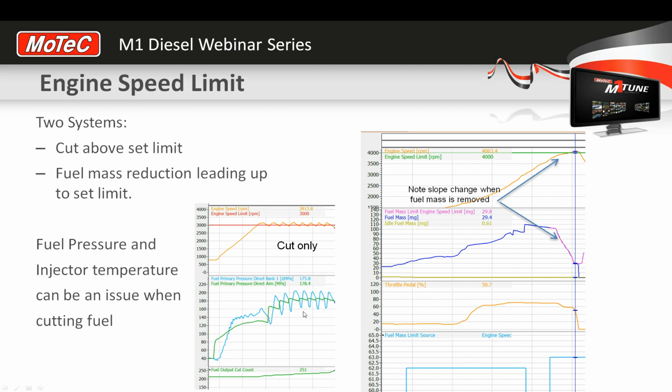In this particular case it's aggressive not only because of the cutting, like an ignition cut, but the main problem here is coming from our fuel pressure control. It's quite difficult for the fuel pressure system to control a dead end rail system. A common rail diesel fuel system is a dead end system, so controlling the fuel pressure very accurately in there with no general return and very, very high fuel pressures involved, it's quite difficult to get highly accurate pressure control.